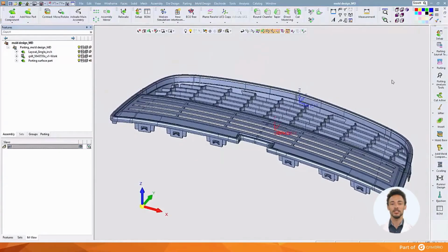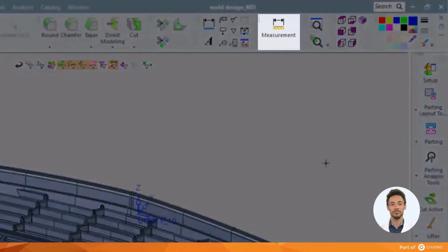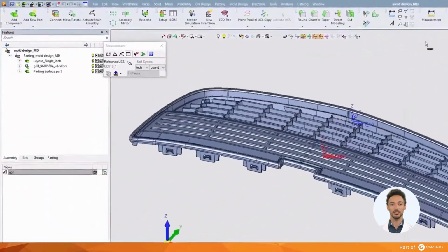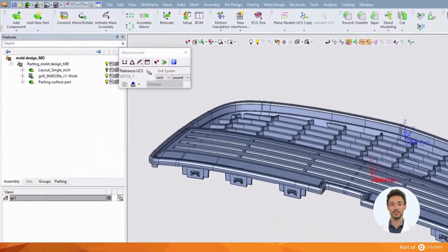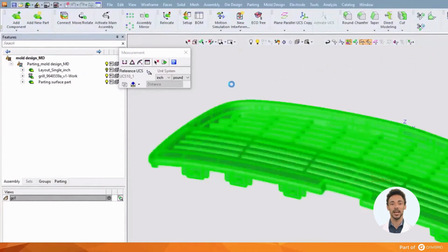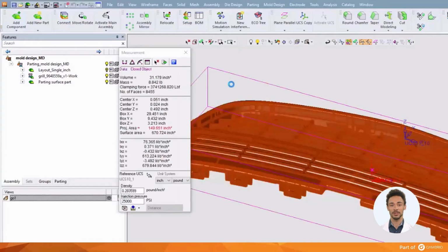Our next analysis tool is used to get measurements. In addition to having nice tools for snapping quick linear measurements, such as from point to point or point to line, it will also measure angles between faces or edges. It can find the radius of curves, individual curves or filleted surfaces, and it will give overall dimensions such as an overall XYZ box, and the mass and the overall volume of the part.